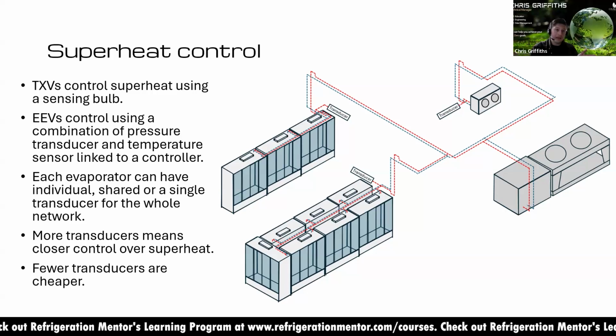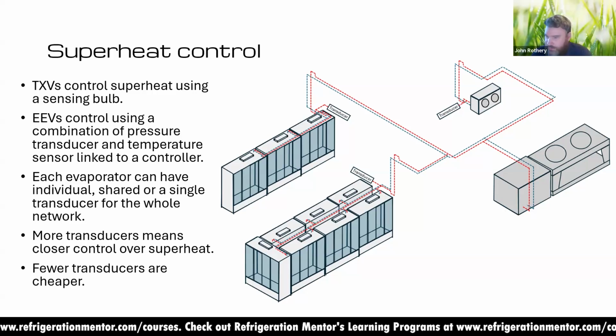Because if 5 are working okay, and yet 2 aren't, you can almost rule out the hardware issue there, because otherwise all 7 would be faulty. Trying to think what else you'd have. You'd start seeing local low superheats on those fixtures that are iced up, so fan strips or something like that.